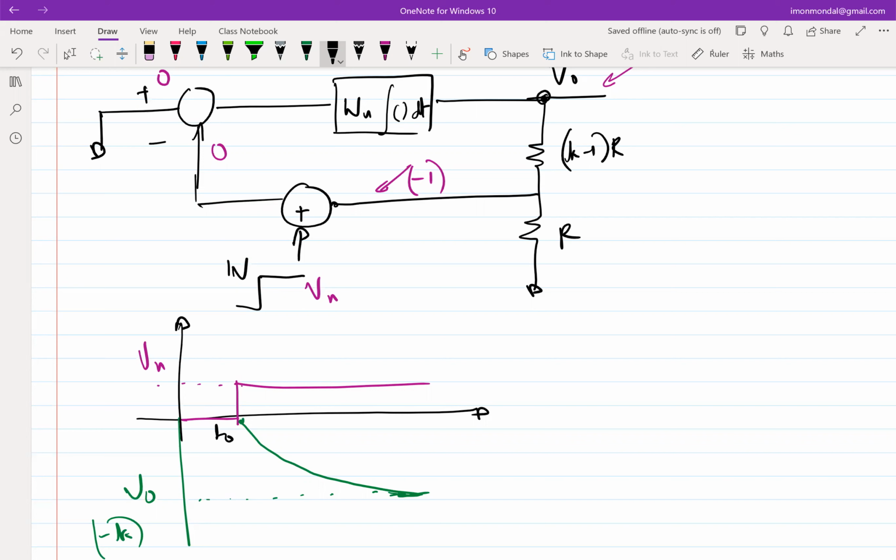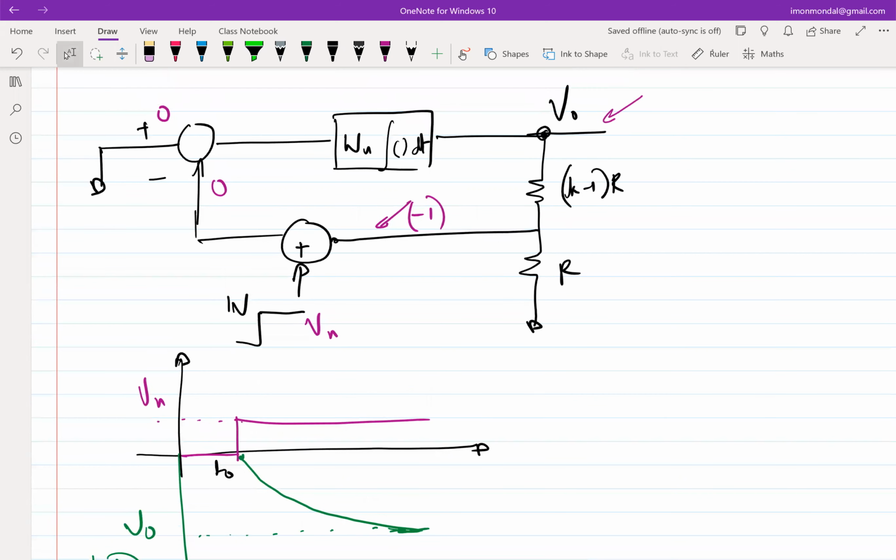So the forward path will define the output. Forward path never defines the output, right? Why do you say forward path is defining the output? The first circuit and second circuit, loop gain is same. Correct. But what we are doing, we are replacing the input in different places. So forward path gain is changing. Forward path gain is not changing, right? When you say forward path gain, what do you mean? Do you mean omega u over s? No, sir. Input and output ratio. Okay, you mean the transfer function between wherever you are applying the input to the output? Yeah, clearly that has changed, right?